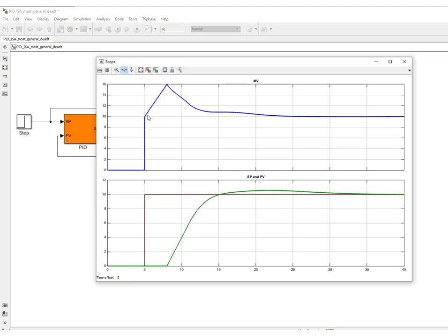So proportional kick, integral action, and you can see over here that we have something that goes against the proportional kick as soon as the system starts to react. And this type of tuning with C equal to 0 is suited for processes with delay as this one.